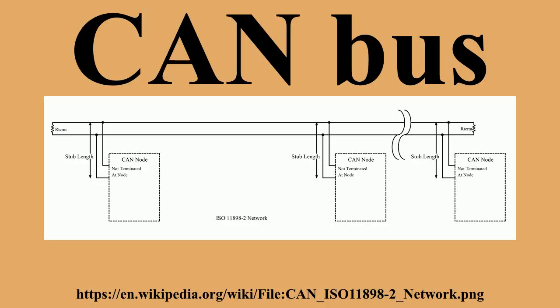As a result, an automotive ECU will typically have a particular or often custom connector with various sorts of cables, of which two are the CAN bus lines. Nonetheless, several de facto standards for mechanical implementation have emerged, the most common being the 9-pin D-subtype male connector with the following pinout: pin 2, CAN low; pin 3, GND; pin 7, CAN high; pin 9, CAN V+.